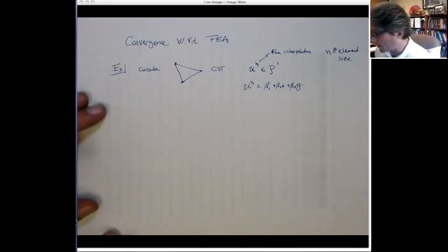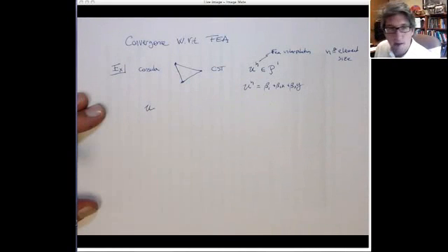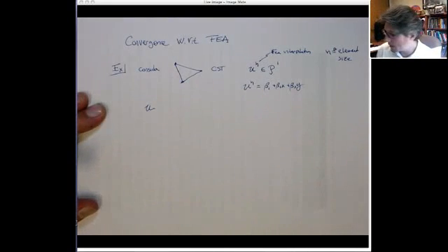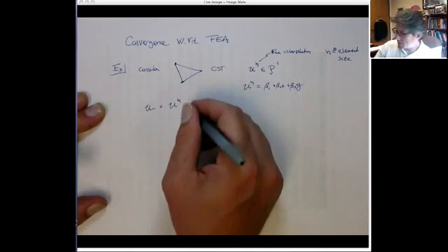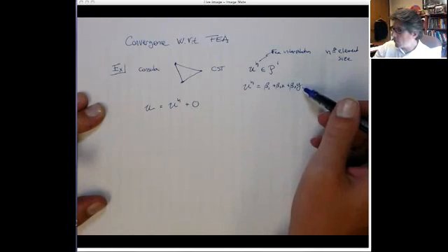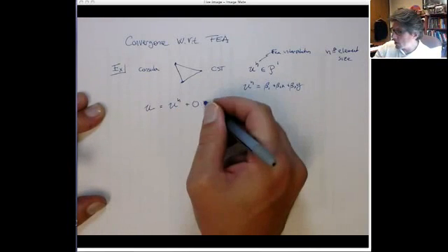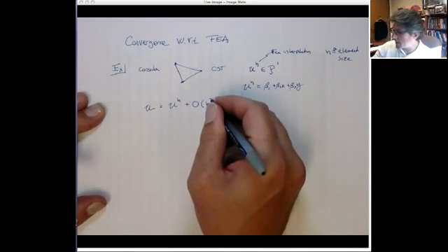So if you think about it, you could have any type of displacement field. So the actual displacement, we can think of it as the finite element interpolation plus higher order terms that are dropped in the interpolation. So for a constant strain triangle, what are we missing here? We're missing things that are quadratic and higher. So we usually write that as h squared.